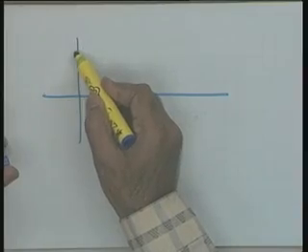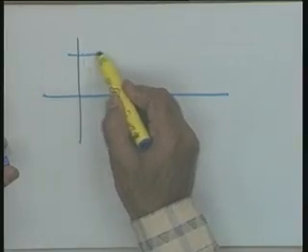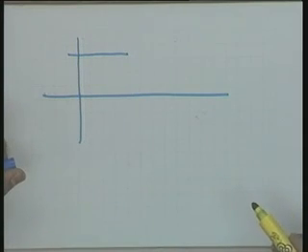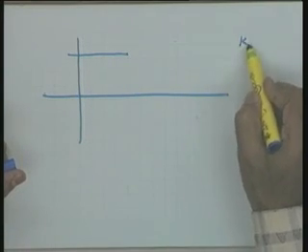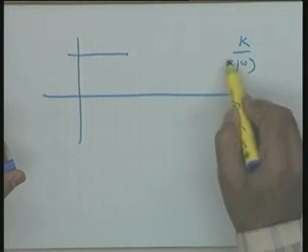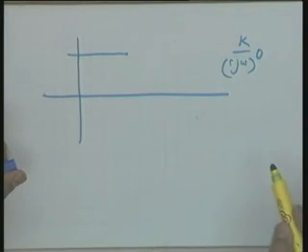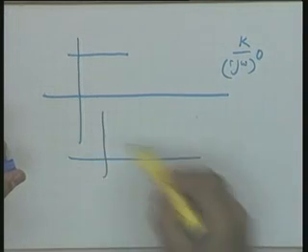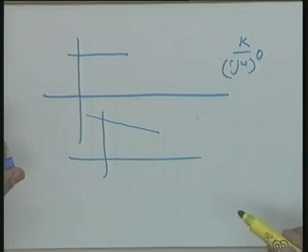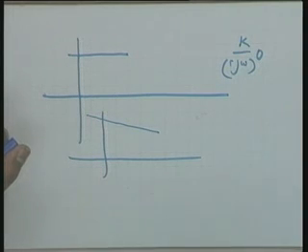the Bode plot, if I give you, if you are working with a type 0 system, in the low frequency range you will find you get a horizontal line. It will simply mean that there was only a constant k and j omega was missing, it is j omega to the power of 0. If in the low frequency region you get a line of minus 20 dBs per decade, as you will see, other factors will add up in the high frequency region, as I will convince you that the other factors of the transfer function will add up in the high frequency region.